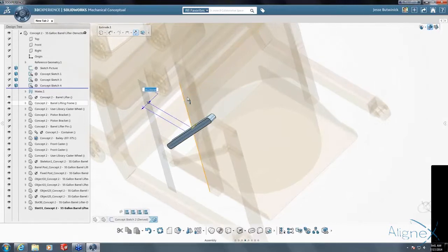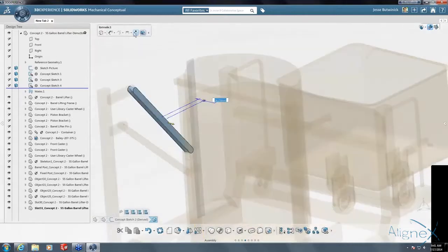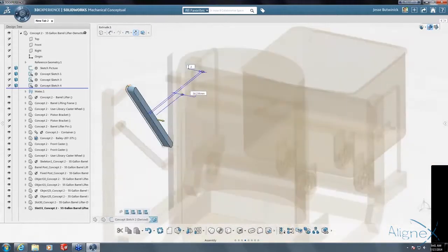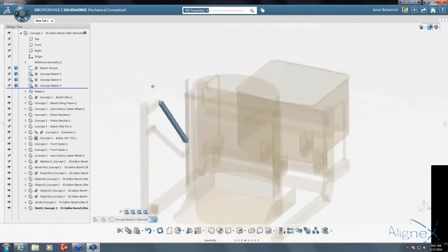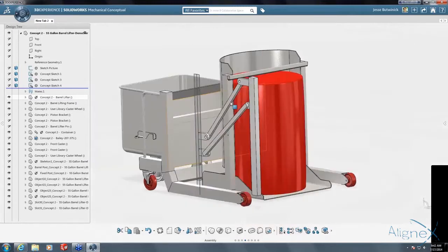And I don't want these components to overlap one another, so we're going to be using an offset. So we have a couple of additional commands here. I want to offset that sketch plane. Actually, yeah, I'm going to offset it at a distance of 20. And then we will specify that linkage to be 20 millimeters wide. All right. So let's go ahead and activate our root. There you can see all of the components have now been created.